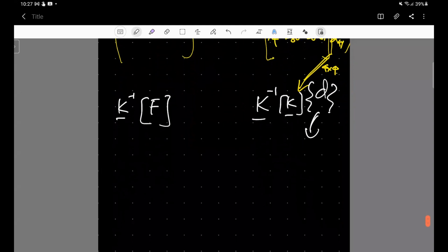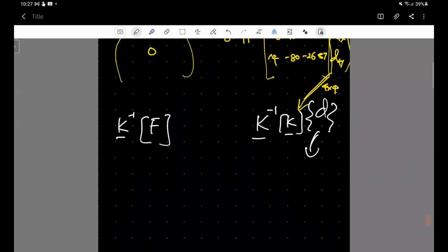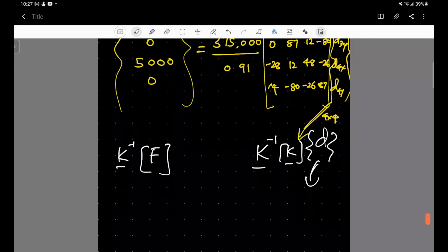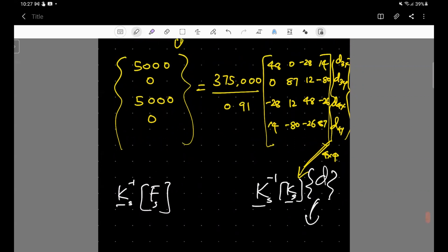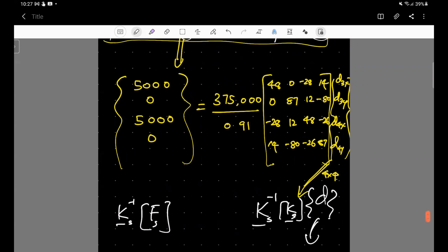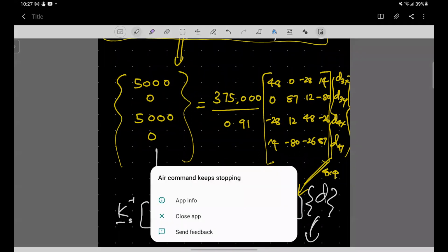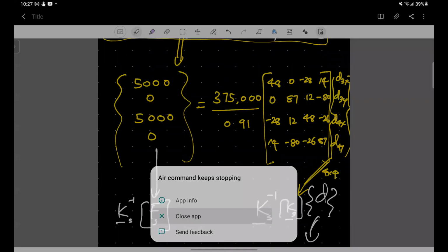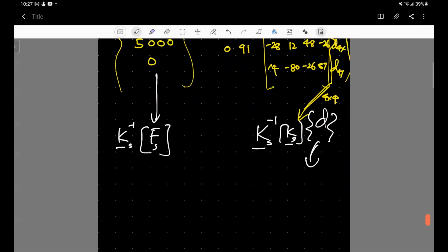Of course, even though I wrote the capital K matrix, it's not the capital K matrix per se. Let's say K sub, you have to take the sub matrix, which is a small portion of the total matrix, of the total force matrix as well as the global stiffness matrix to calculate the displacements.